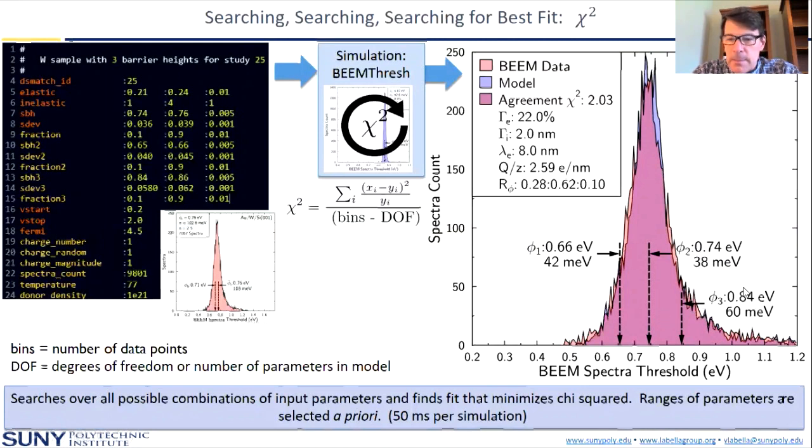And here we're seeing about 0.84 come through, and that's from the gold cap. We actually have to cap these with gold to prevent oxidation. The non-uniformity of the tungsten silicide, which was deposited by e-beam, allowed maybe some areas for the gold to come through. Again, we deposit all this in UHV and then put the gold cap down. So the tungsten silicide was partially reacted, and after we put the gold down, we got a mixture of the two. All this interesting detail is missed if you're just averaging a spectra or just doing IV. And that's the insight we get out of that.